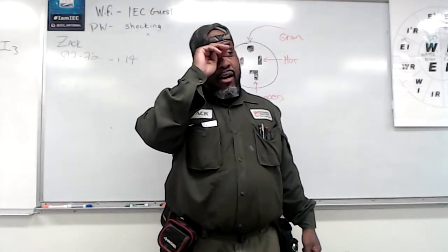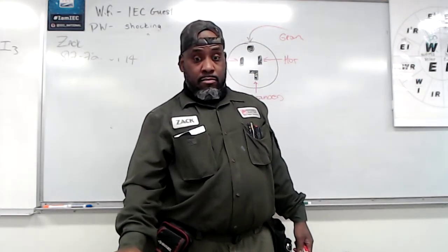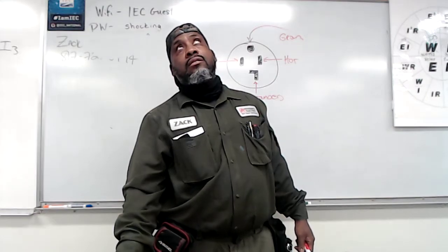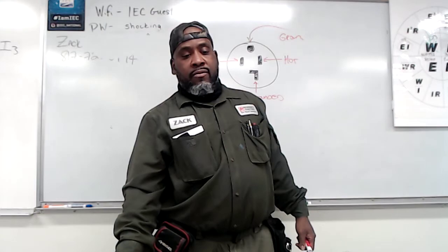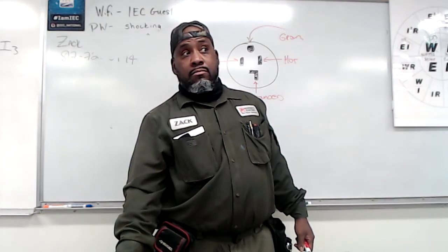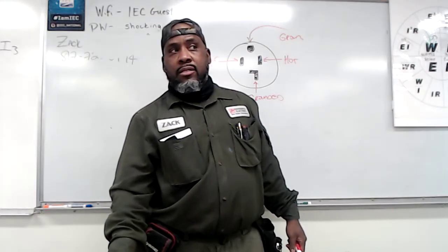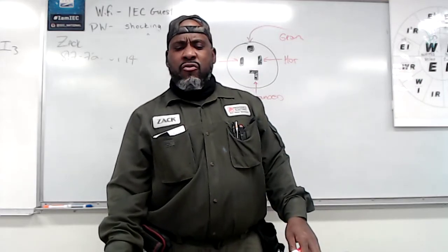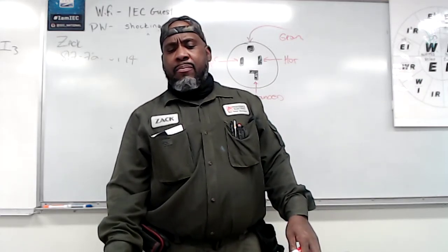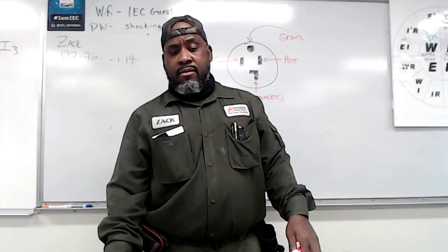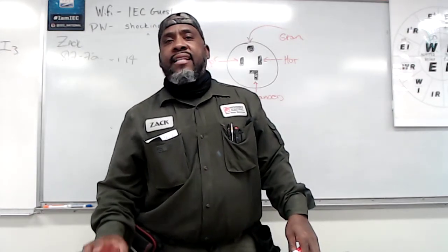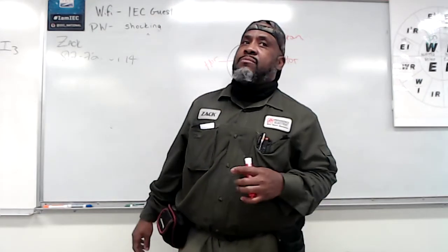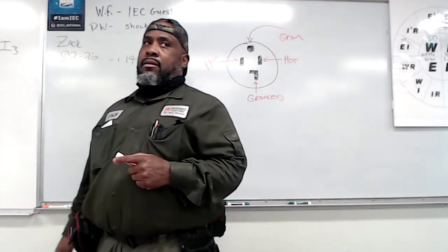What's this, a 14-50R? That's a dryer plug. No, that's an oven plug. 42 is an oven plug. 41. That's dry. Oh, it's a dryer plug? Why is it 50 amps as a dryer plug? A dryer plug should be 30. No, the L is a dryer plug. Oh, yeah, because it's 30 amps. That last number tells me how many amps that plug is rated at. Okay?